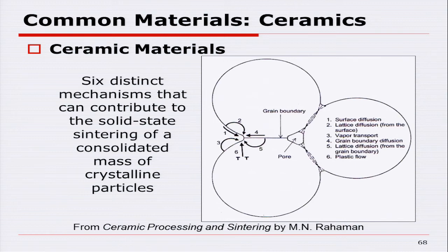Now understand that vitrified refers to liquid sintering. So that's another term for liquid sintering. When things start to melt, liquid sintering is called vitrification. So that takes place, and you get a more glassy finish and one that's non-porous. Now, in most clays, what we'll typically do is we just do a solid state sintering, and we get this really hard pot. And then what we do is we come back and we put a glaze on the pot.